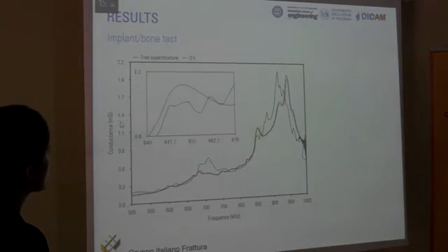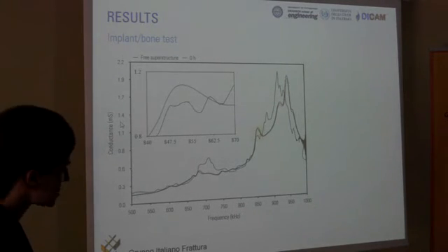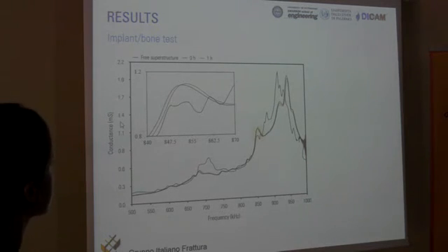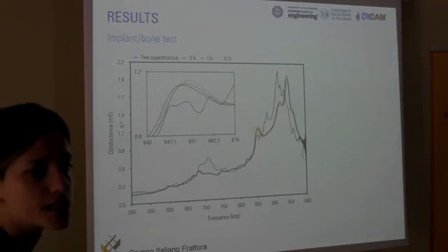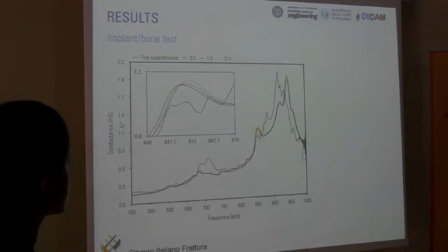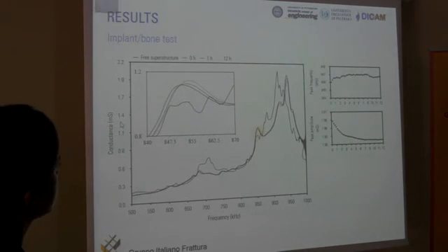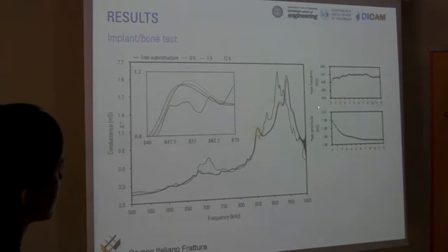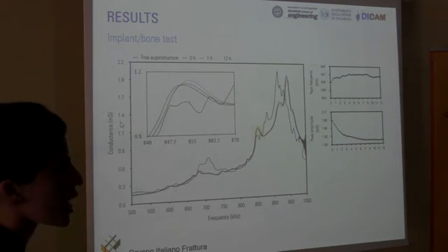And if we focus always on one peak, the one underlined in yellow there, we can see a certain shift toward high frequency. And in these graphs you can see the behavior of the main resonant peak of the piezoelectric transducer. We can see that there is also an asymptotic increase in the frequency and a decrease in the amplitude.